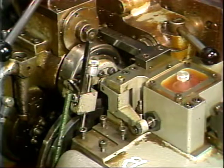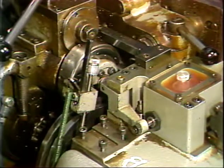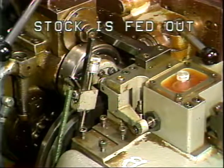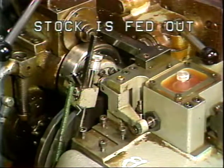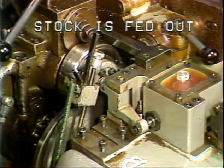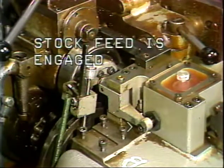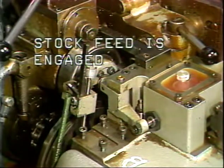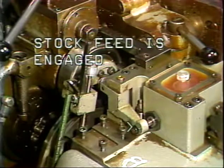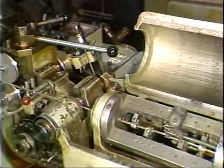The stock feed cycle has two portions, the stock feed portion and the stock feed attachment return portion. During the stock feeding portion of the cycle, the friction clutch is engaged and stock will be fed out. At the start of the return portion of the feed cycle, the friction clutch cam will disengage the friction clutch by moving the hydraulic plunger into the hydraulic control unit. The feed attachment will then be fully returned. After the stock feed attachment has been fully returned, the friction clutch cam will allow the hydraulic plunger to release the hydraulic pressure. Spring pressure in the friction clutch assembly will engage the friction clutch. Stock will again be fed out and the cycle will repeat.